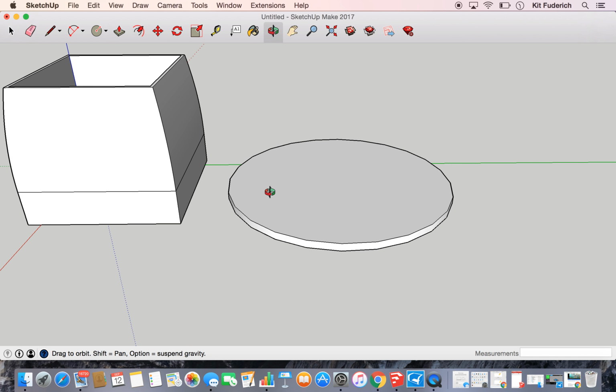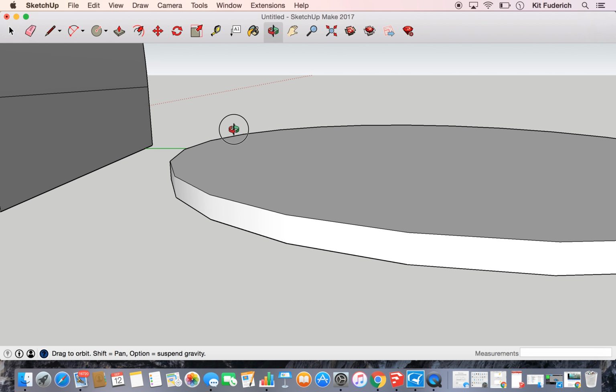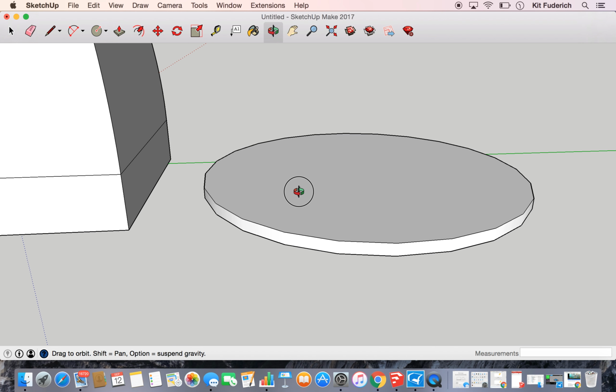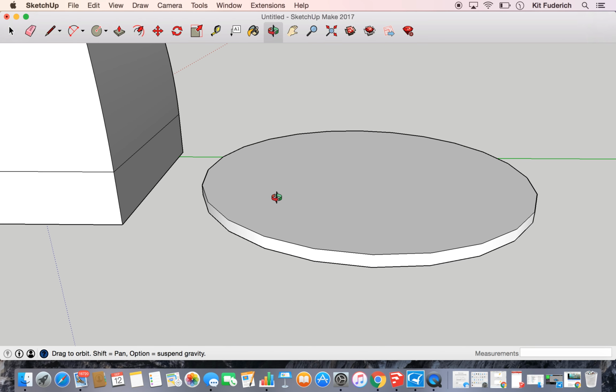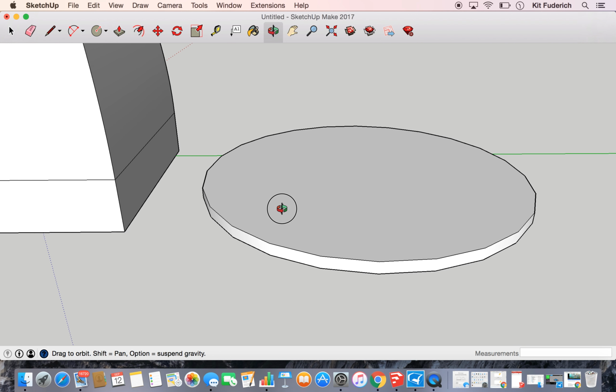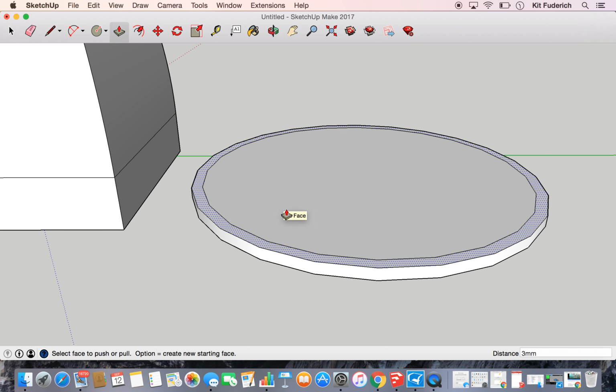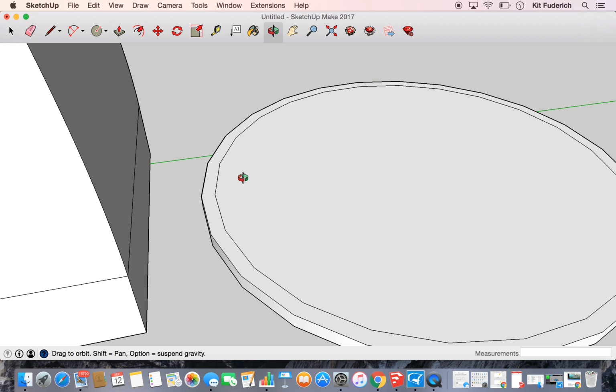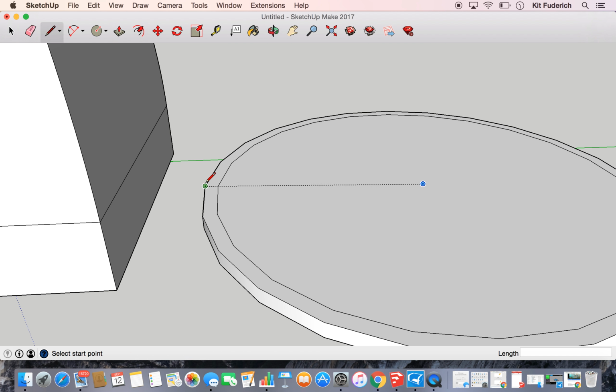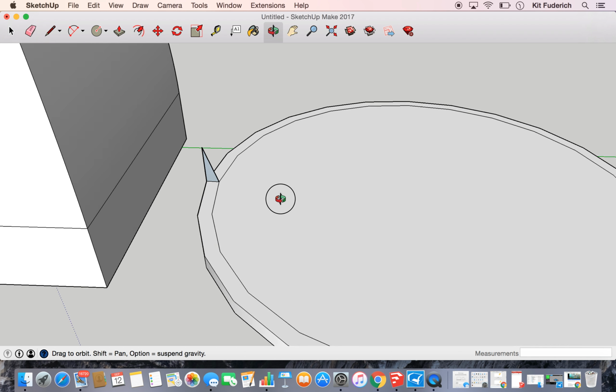From here I'm thinking, alright, it's much better if this is a rounded edge at the top, because right now this isn't a tray at all. And in fact, I should probably increase the diameter of this tray slightly for this curve. So I'll take the offset again and take the most bottom edge, drag out, and then extrude up again and move so I match the plane. Now from this perspective I'm going to take the line tool, the pencil tool, move to an endpoint, move upwards along the blue axis, select once, and then click down and across so I create this sailboat-like shape.